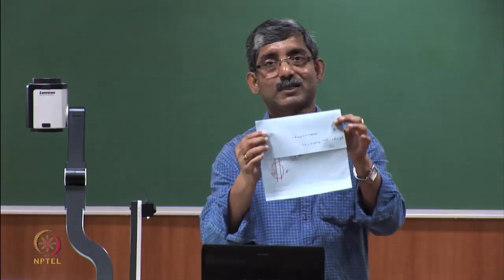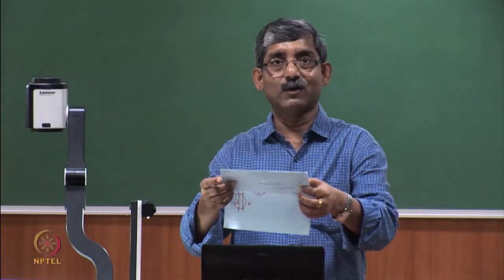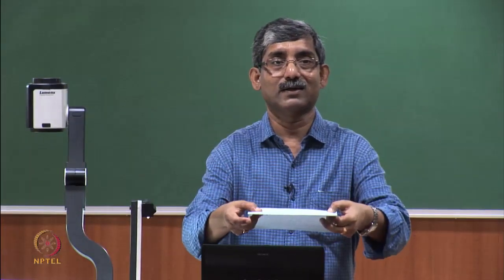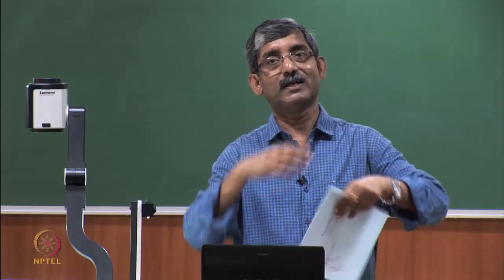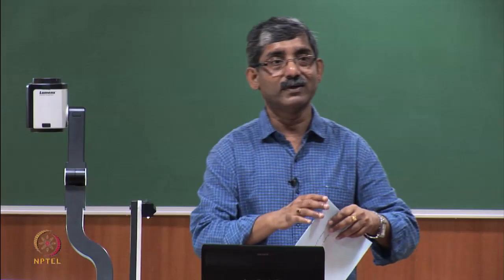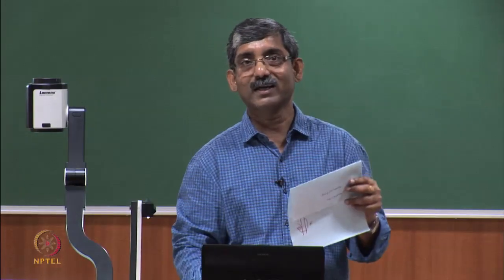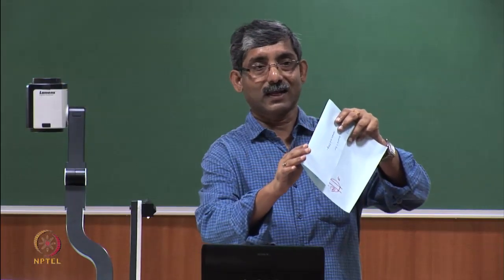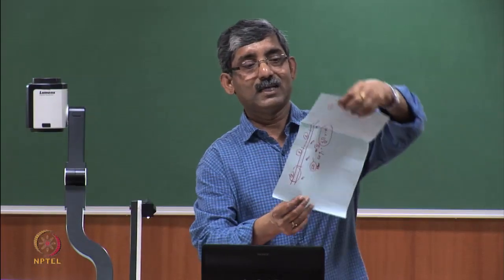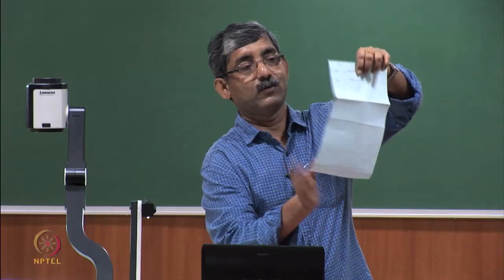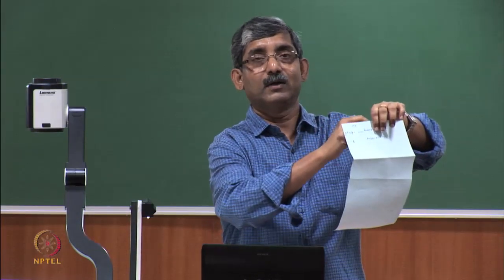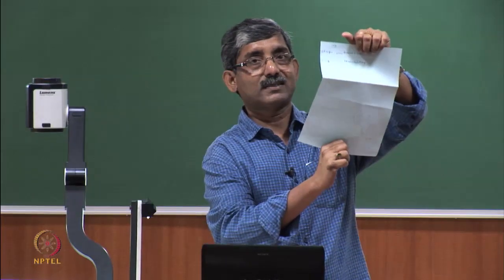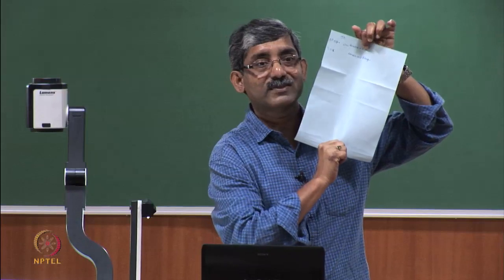and keep it. This specimen, where the folded edge is there, we place into the testing chamber, where this specimen is tested and rubbed against the edge. Then after a certain number of cycles we take out this fabric, remove the stitch, and test this fabric for the grab strength.